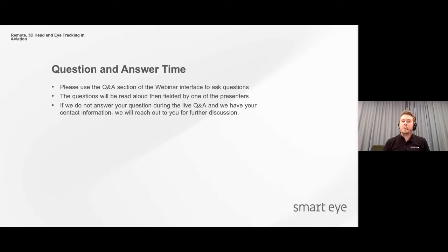But if we are, then our synchronization box that basically triggers both the cameras and the illuminators is able to either send that trigger signal for another system to desynchronize from ours, or receive a trigger signal so that we can desynchronize our system from the other system. Since our exposure time and the time that the illuminators are on is very short, there's plenty of time that we can desynchronize to.